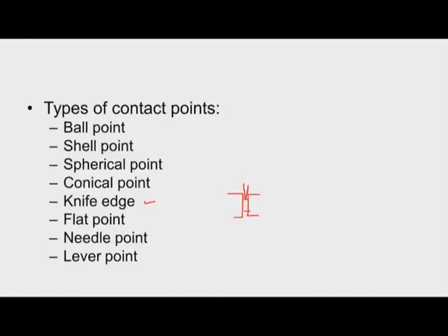Similarly, for the spherical type, the contact point will be like this with a larger radius, and when the workpieces are pushed from the sideways, then such spherical type indicators will be very useful. Also there are lever type indicators which we will be discussing after some time.